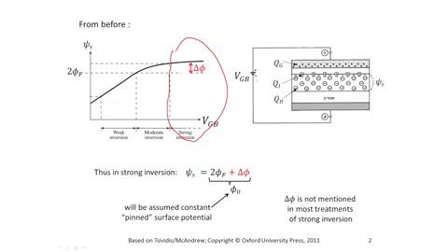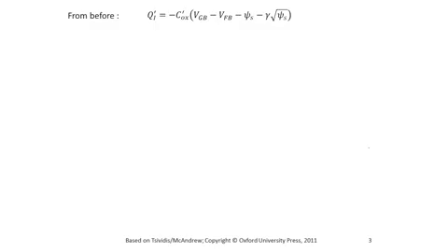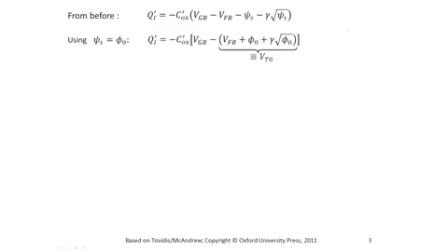So now I'm going to use this value for the surface potential, φ0, inside the simple equation we had developed for the inversion region, which was this one. If you go back to our general treatment, we had developed this equation, which is valid throughout inversion, weak, moderate, and strong. Well, in strong inversion, we can replace ψS by φ0, and we end up with this. Now this, if you lump all of these terms into one, and you call the result VT0, this will turn out to be the so-called threshold voltage, then this equation can be written simply like this.